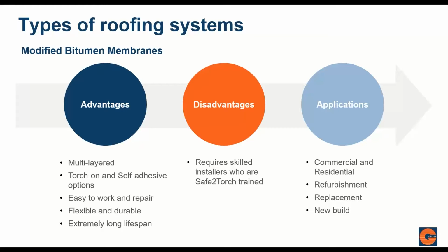Bituminous membranes are very easily workable and easy to repair. You simply apply heat and you can make repairs relatively easily. And the products are very flexible and durable. They have a huge longevity and last particularly long in comparison to some of the other products available on the market. One of the disadvantages is these do require skilled contractors to install,